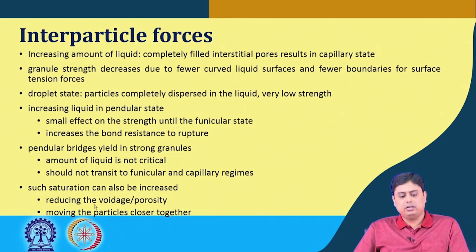The granule strength decreases because there are now fewer curved surfaces. The capillary pressure and all these are important, but fewer boundaries are there that were responsible for the surface tension forces.